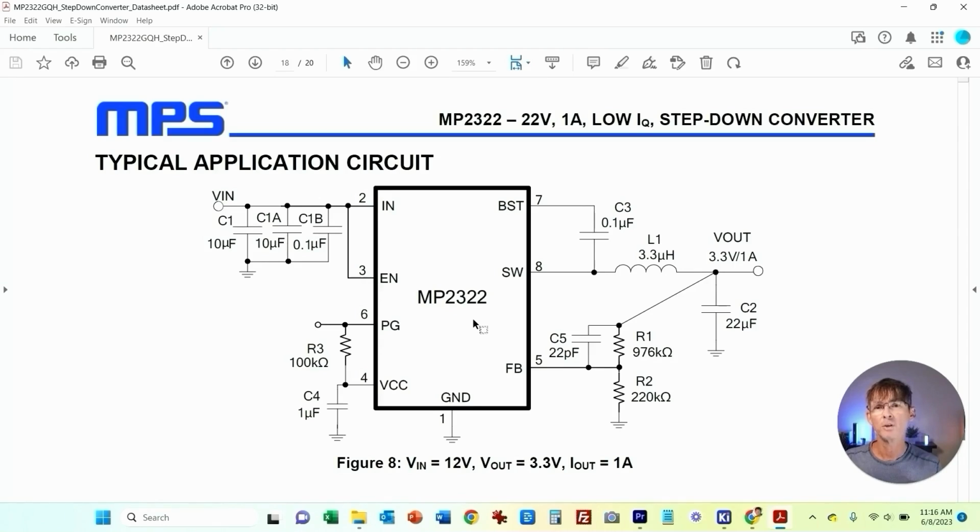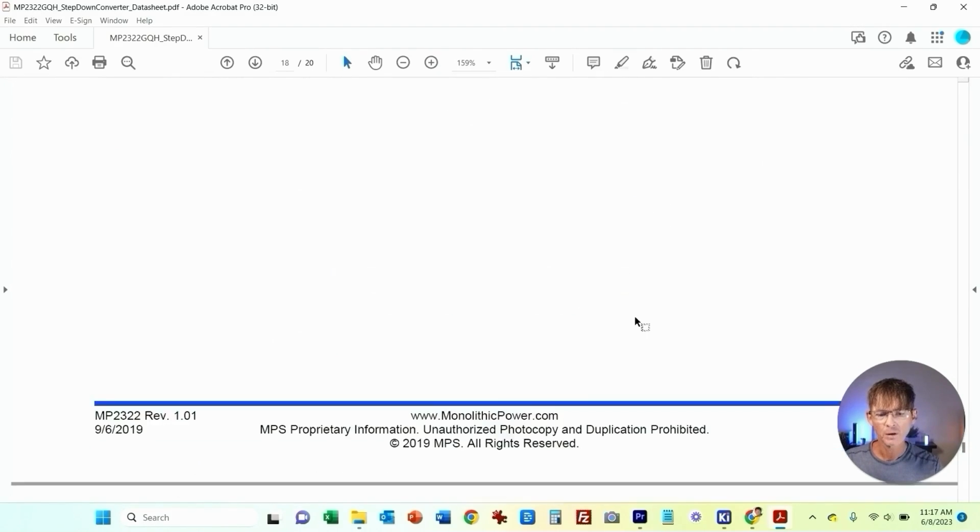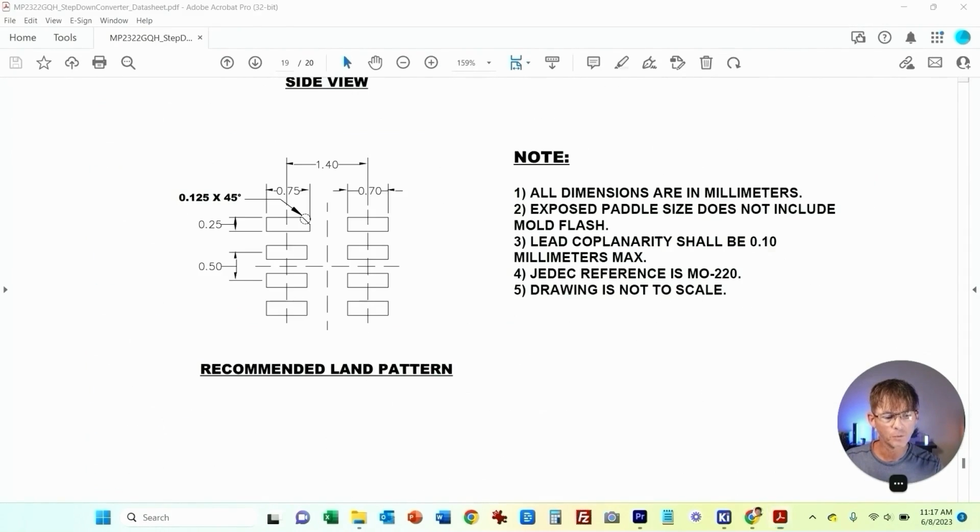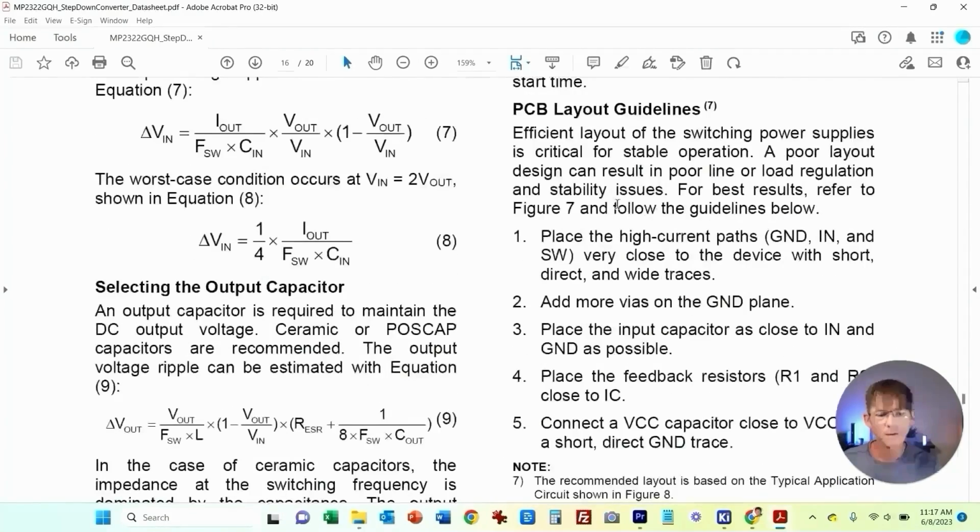And I would encourage you to stick with a switching regulator that has a data sheet that gives you that example layout. That's going to make things a lot easier for you. I don't know the exact percentage that have it. Most switching regulators tend to have an example of the PCB layout since it's so critical, but I know all of them don't. I've seen some that don't. I would encourage you to try to find one that does have that, just to make your life a bit easier. Okay, so let me see where, yeah, here it is.